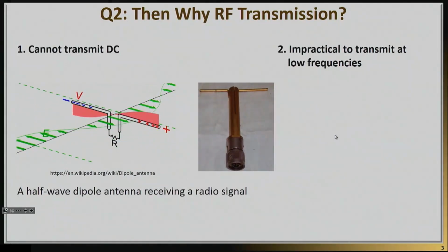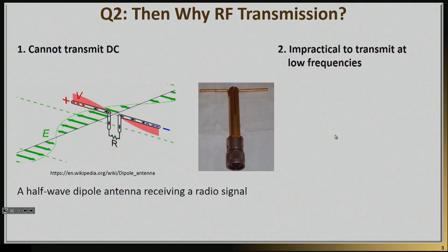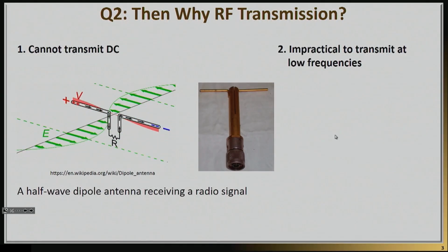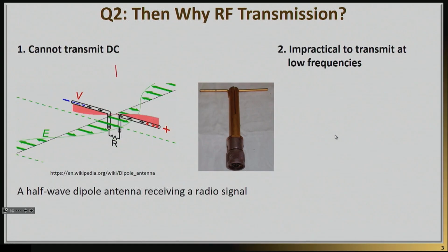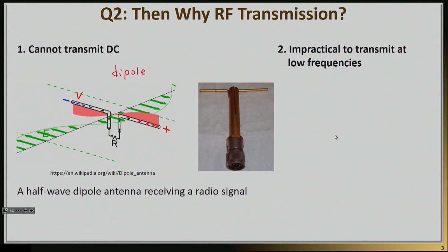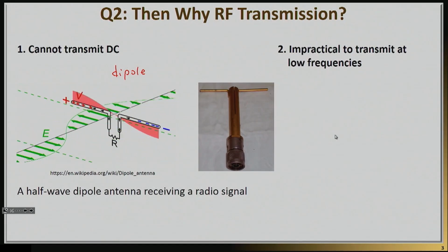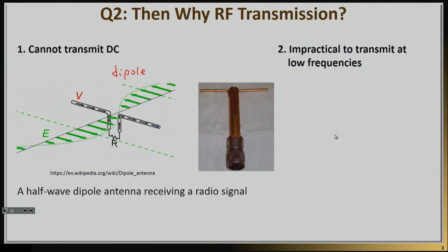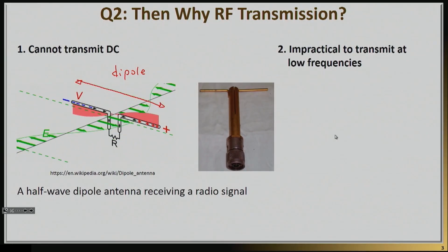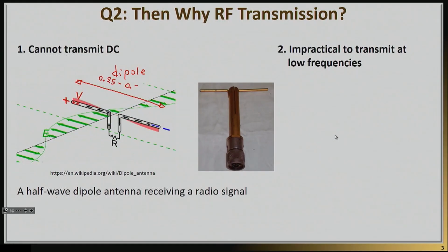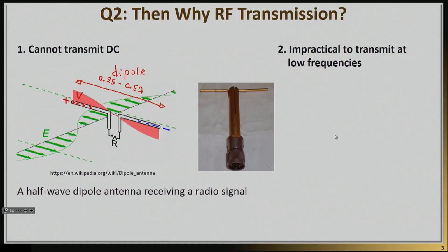So the first thing that I have here is that there are some fundamental difficulties regarding antennas. Even if you have not taken an antennas course, what you probably remember from fundamental electromagnetics is that for a structure like this dipole antenna to efficiently radiate a signal or efficiently receive a signal, it needs to be somewhat large. And what we mean by somewhat large, I mean somewhat large compared to the wavelength. And the rule of thumb is that most antennas that basically transmit efficiently have to be somewhere between a quarter of a wavelength to half a wavelength. So lambda there is the wavelength.